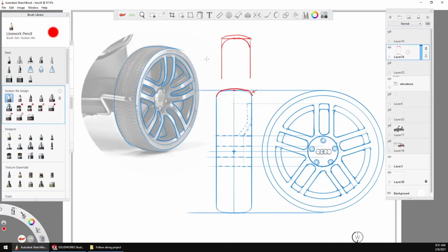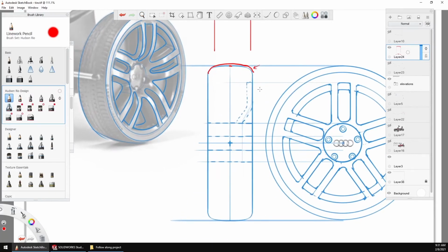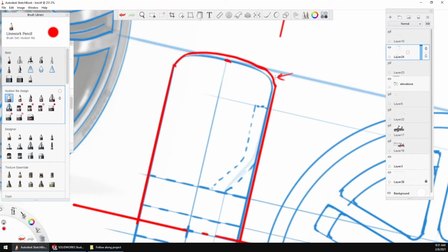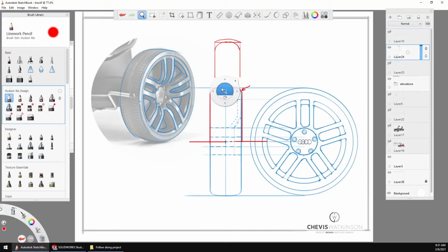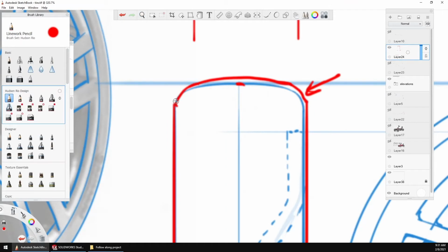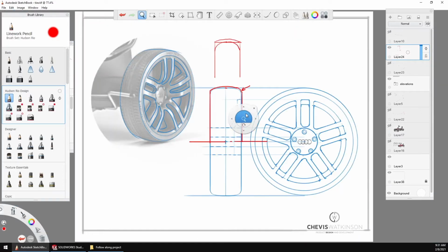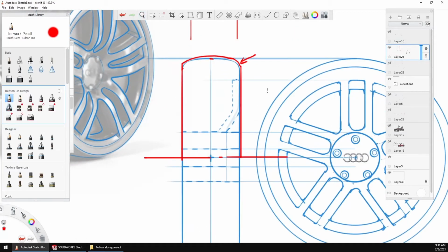So if I look at this, I'm going to say the biggest thing is I can do a simple revolve of a 2D profile that looks like this. Now, whether I put that radius in the sketch or whether I do it as a hard point or a hard corner and add the radius later, we'll get into the different logics of that.